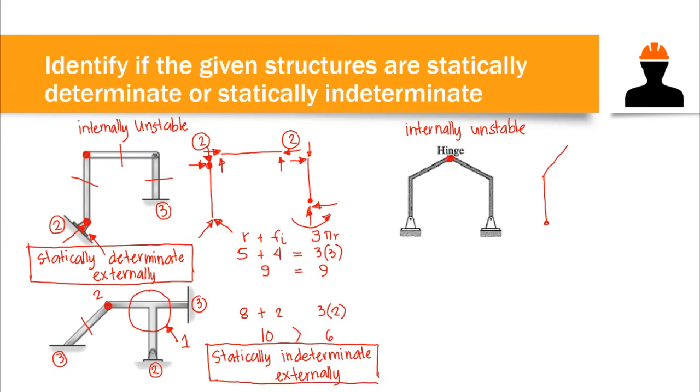Okay, now let's draw the free body diagram. At this point, we have 2 reactions, since again that is a hinge. And this one is an internal hinge, so we have here 2 internal forces, the same as with the other side. Again, this one is symmetrical. We have a rightward force and a downward force. And on the right end or right hinge, we still have 2 external reactions or forces.